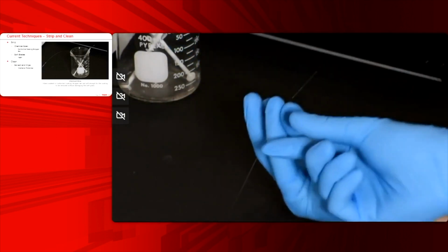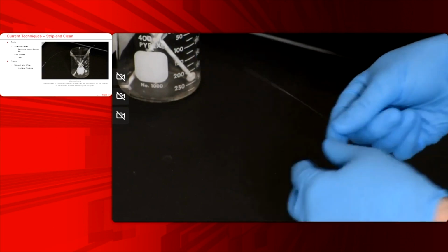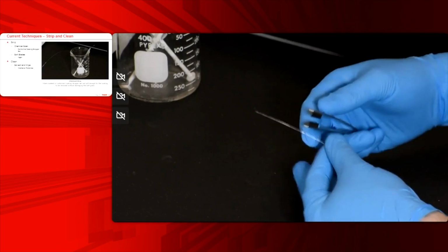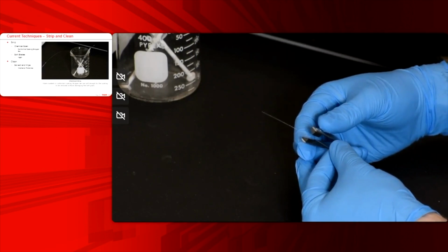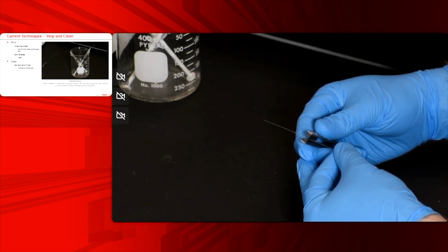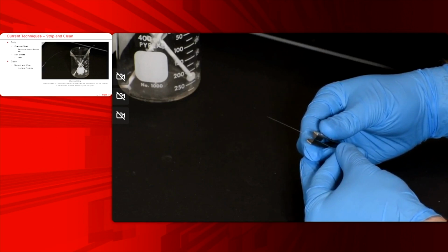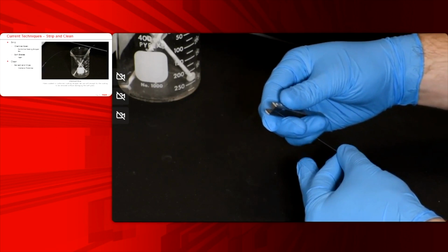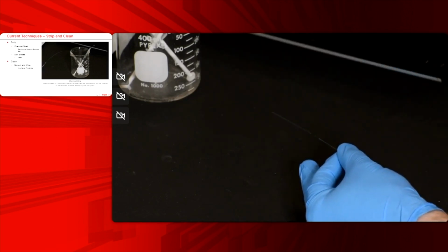And the soak that I've used is a conformal coating strip gel. I have about 0.7 milliliters just drawn into a syringe. That 0.7 is just to give me the length of strip that I desired. This coating, I think, soaked for about 2 minutes before this. But there I just pinched the coating and removed it without damaging the glass underneath.